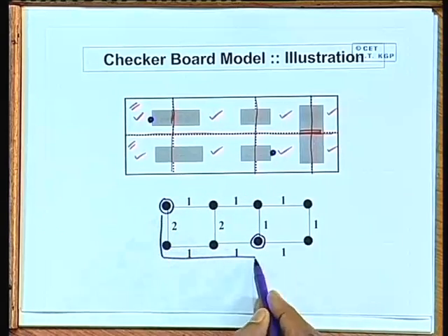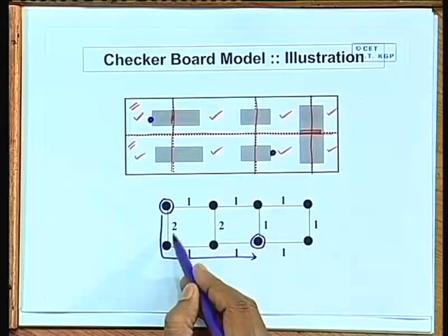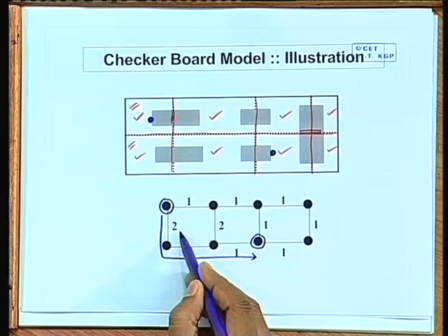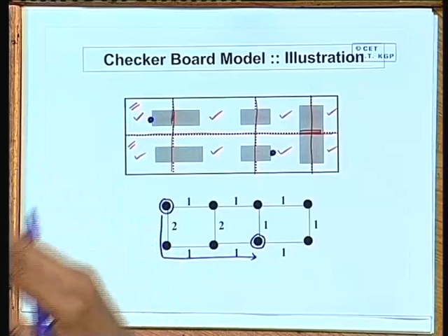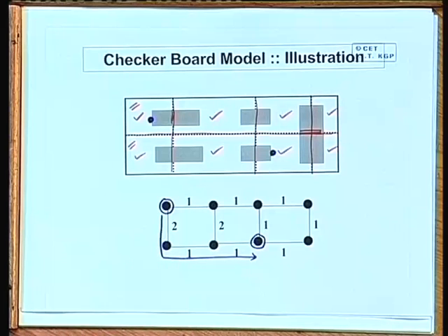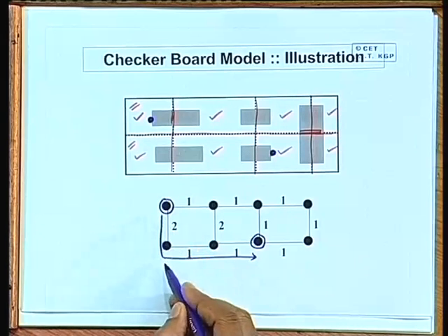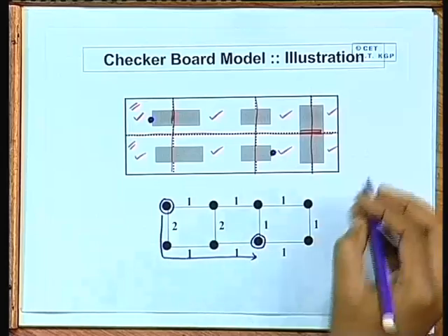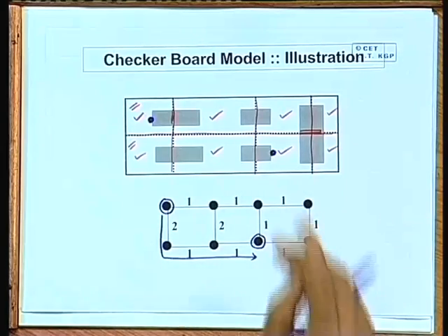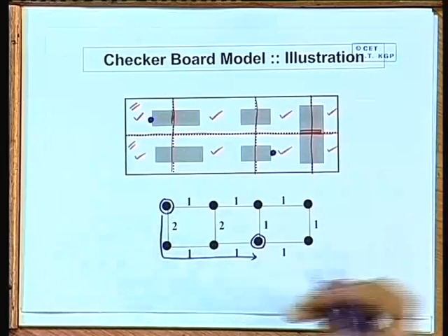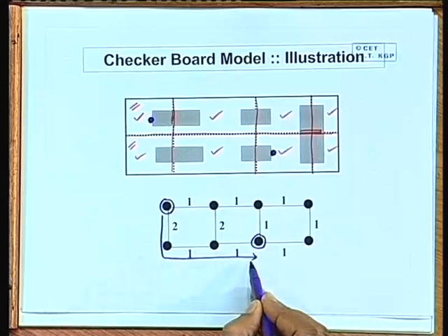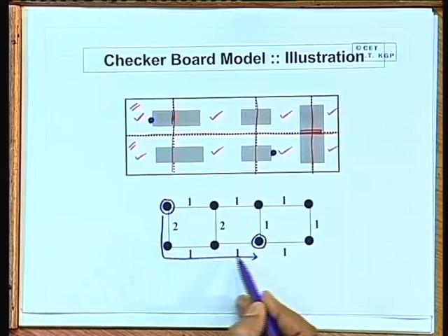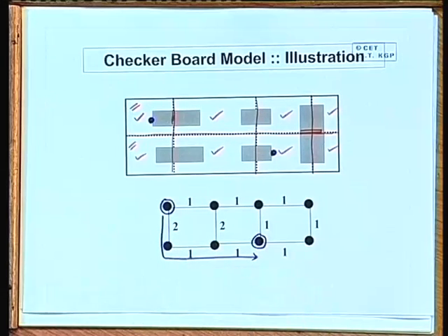Suppose one wire has been routed through this channel which initially had a capacity of 2, the residual capacity will decrease. If each line you interconnect contributes a capacity of 1, if you assign the numbers in that way, then whenever you route a net, you decrease the capacities along that path by 1.